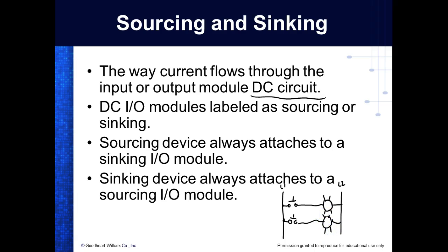I'm just using lights right now. Now, if this is DC, which is going to be plus and which is going to be minus? Doesn't make any difference. Current's current. Light bulbs don't care, relays don't care if it flows from left to right or right to left. So if I come over here and put the plus right there, and the minus over here, which most people want to do, then notice this is the common right here.